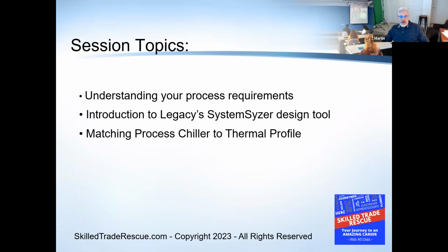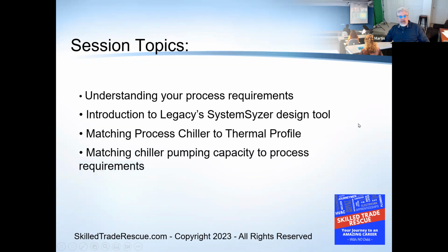Next is matching the chiller requirement to the process thermal requirement. I talked about that a few minutes ago. And then the other one is pumping. Pumping is a big deal, obviously. Even if you have a chiller that has enough cooling capacity, you have to make sure that you have enough capacity on the pumping side to get that capacity out to the process load.